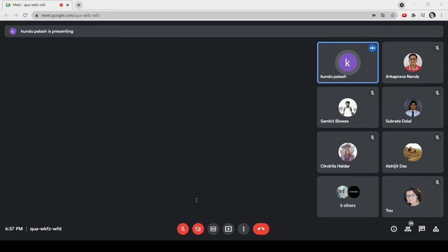For timer operation, the C/T bit should be 0. Now, what is the counter operation? And to generate the time delay, these are the steps which I have described just now. When we learn the 8051 instructions, the programming segment will be clear. Now, what is a counter?